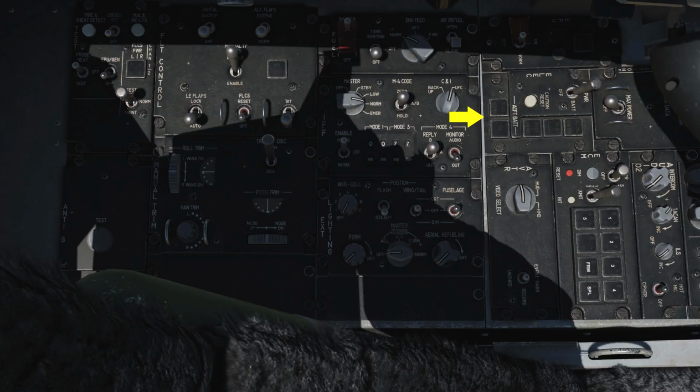Along the bottom of the panel are the aircraft battery indicator lights. The fail light comes on if there's less than 20 volts in the battery when airborne or battery failure on the ground. The TO FLCS light illuminates. It means that one or more branches is getting less than 25 volts while airborne, or battery power is going to one or more FLCS branches while on the ground. And the FLCS relay will illuminate if one or more FLCS branches is getting less than 20 volts, or one or more are not connected to the battery.